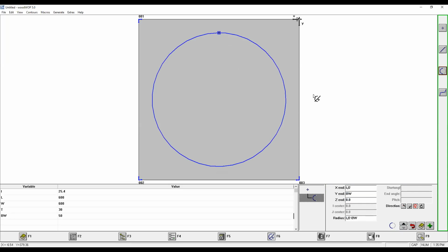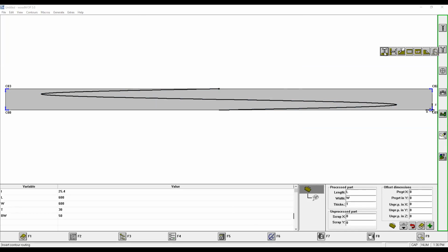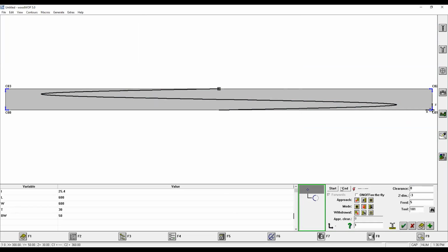There's my full circle, but if I go to the view, I started here at the thickness of the board. In one swift motion, I ended up down at the bottom of the panel. So again, when you go to your router bit, it's still an open contour. Tell it where to start, where to end. Vertical in this case, maybe I want to cut to the inside of that. So I would cut left, vertical out, and again at 0. Select the tool number.